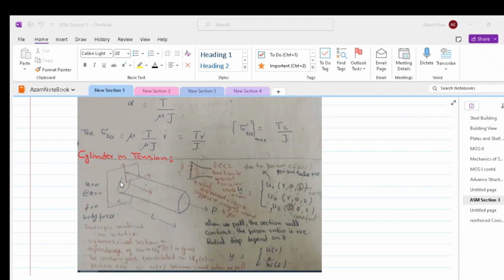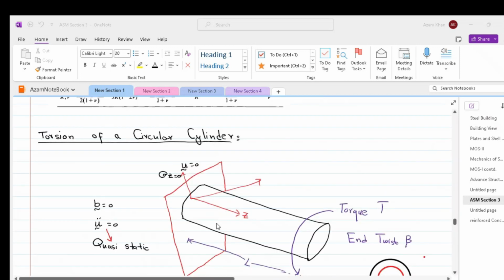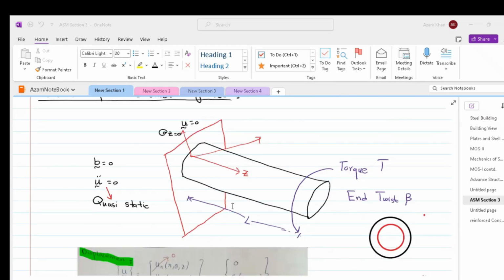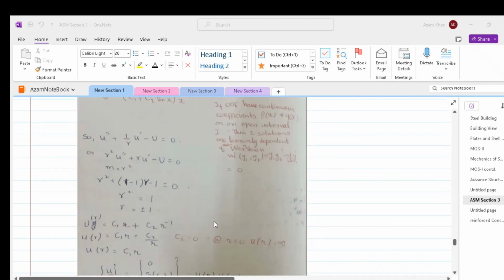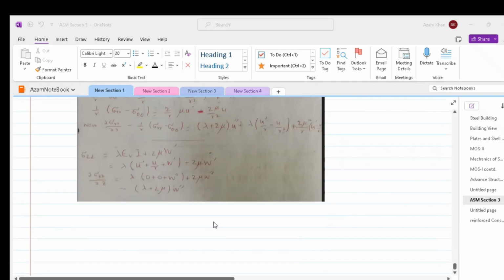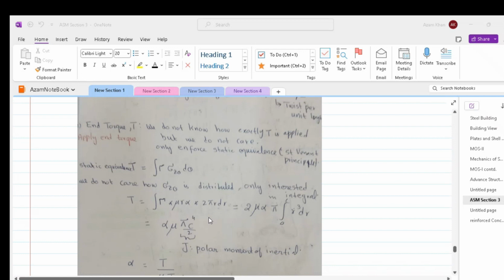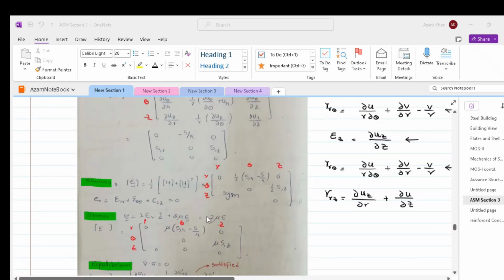We now use displacement formulation to get the internal stresses, strains, and displacement of a cylindrical structure cantilevering out, having a length L, and subjected to a tension load P. This problem is similar to the torsion problem we discussed previously. So instead of torque tau, now we have a tension load applied at the free end of the cantilevered cylinder.